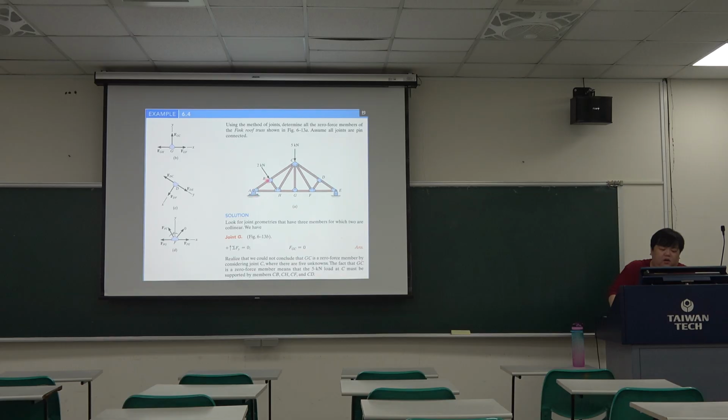So every part has just a parallel direction force, and we have the hinge support here. So we have reactions in this direction and this direction. And we also have the roller support here, so we also get the perpendicular reaction here. And then we also have the two forces.